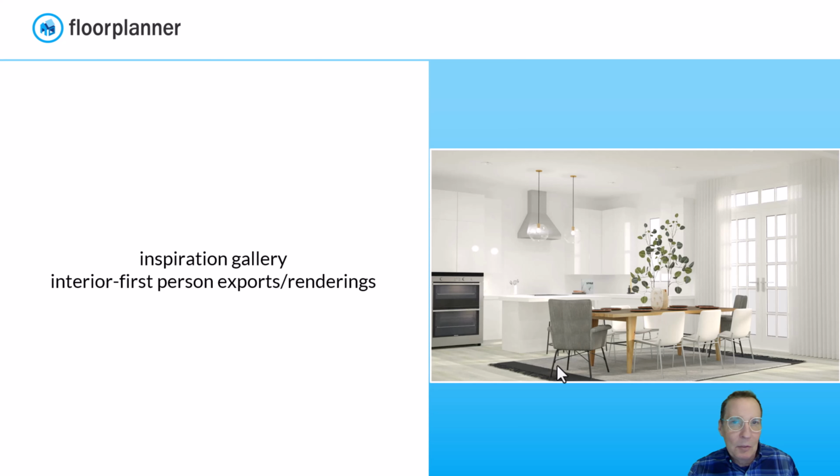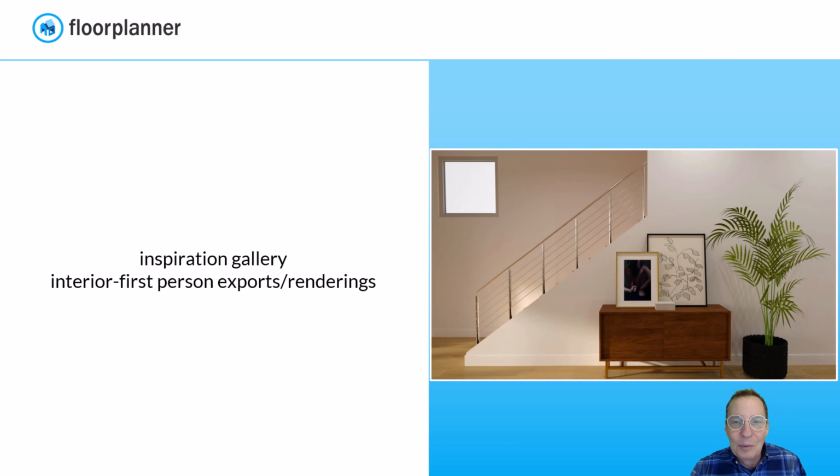And just some talking points on the way out. Don't forget that your three-dimensional items, your objects inside Floor Planner, play very nicely with each other. You can rescale them, you can overlap them. So out of about 300,000 plus items that you have inside Floor Planner, mix and match them, resize them sometimes to create something you don't have in Floor Planner. And now you know that you can also create a named group of that new item that you've created for its reuse. Camera views and different settings.